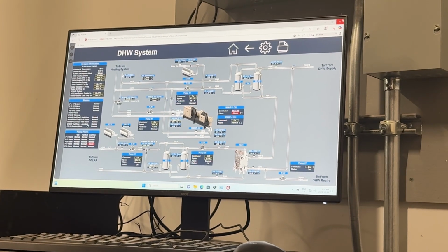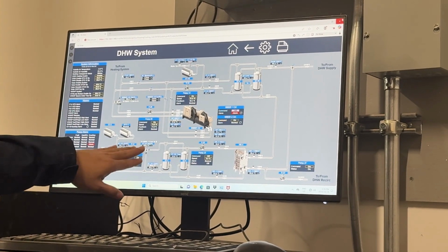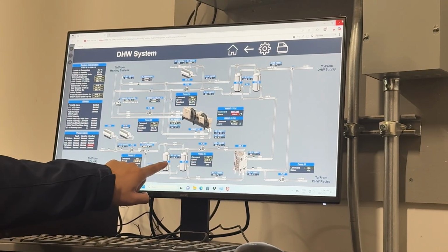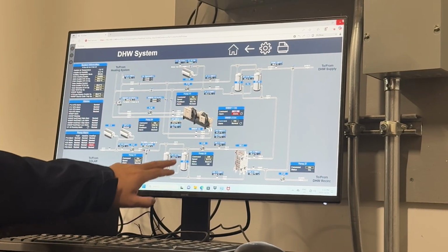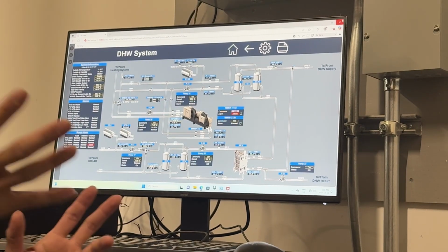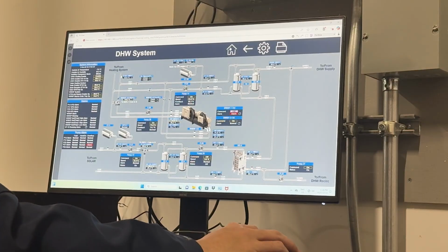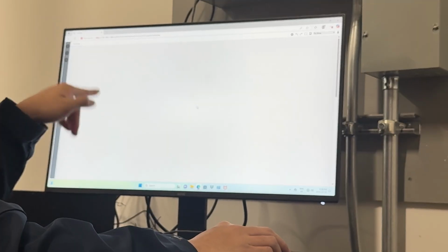There's not enough sunlight. Otherwise, the solar will steal heat from the storage tank and then bring the heat to outside, which is a waste of energy. Yeah, that's for the hydronic loop on the heating side. The pressure will be on the heating loop and the cooling loop.